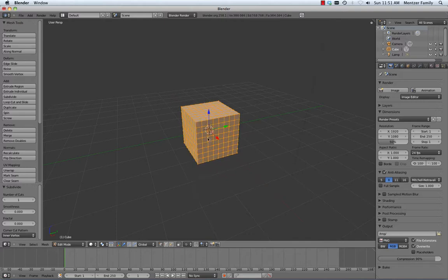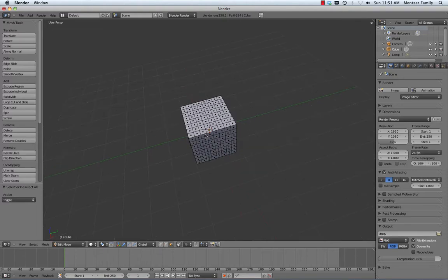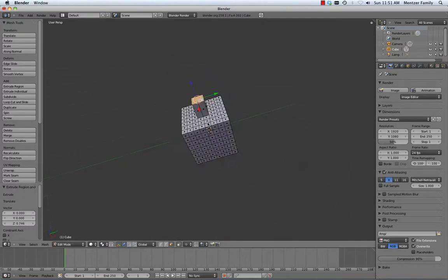And by doing that, you end up with a lot of resolution. So if my idea then is to make, say for example, let's do a kind of goofy, simple robot shape. We'll unselect all and jump into face select mode by hitting Control Tab and choosing face. Then I could grab just the faces that I'm interested in. Let's grab, shift clicking here to grab multiple faces with these nice little control points that sit in the middle of the faces. And I can extrude up then by hitting the E key and give myself, for example, the neck or the head of that object.